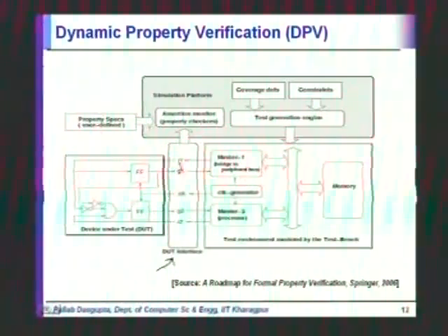So my signal R1 here may be called as REQ1. Okay. So the binding is telling us that R1 is REQ1 here, and on this side maybe this is called as Z1. So we are saying R1 is Z1. Okay. So that's how you bind the thing together, and this interface is what is made visible to the assertion monitor. Right.